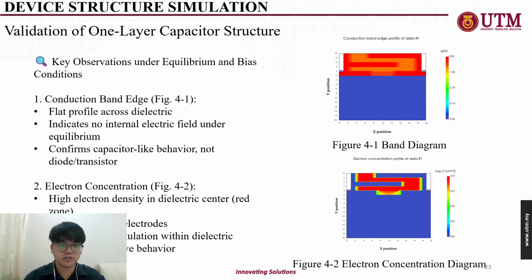And going to the device structure simulation, first we can see from figure 4.1, which is the band diagram. So actually it provides a flat profile across the dielectric, which indicates no internal electric field under equilibrium. So it confirms the structure acts like a capacitor, not a diode or transistor. Then figure 4.2 shows an electron concentration diagram. So there is a slight drop near the electrodes and high electron density in the dielectric center.